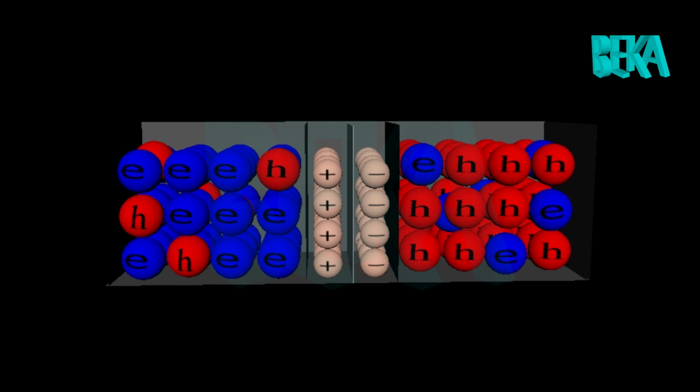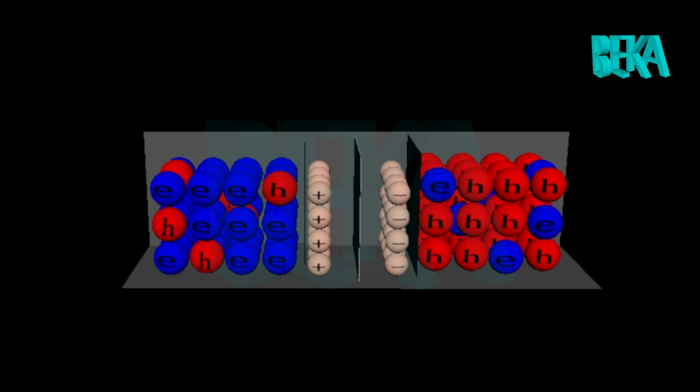Eventually a state of equilibrium will occur, producing a potential barrier zone around the area of the junction as the donor atoms repel the holes and the acceptor atoms repel the electrons. This area around the p-n junction is now called the depletion layer. As the N-type material has lost electrons and the p-type has lost holes, the N-type material has become positive with respect to the p-type.